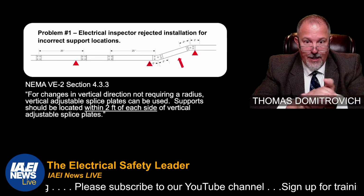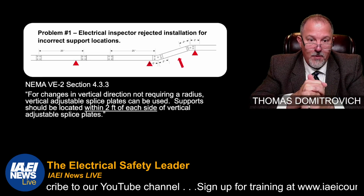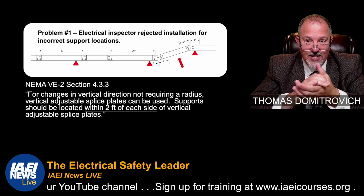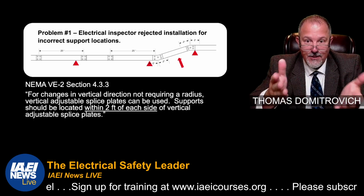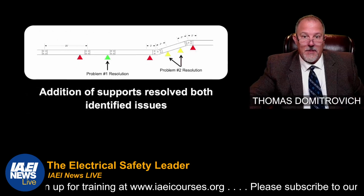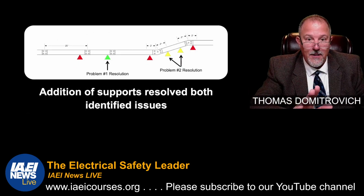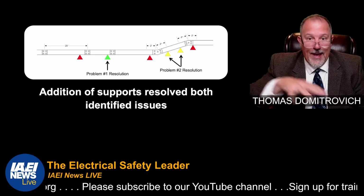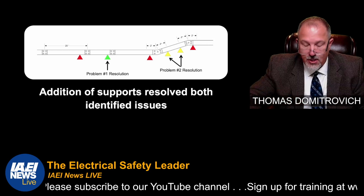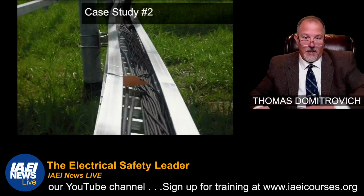Where not requiring a radius, vertical adjustable splice plates can be used. Supports should be located within 2 foot of each side of vertical adjustable splice plates. Look, there's another missing splice plate. This would have been the proper way to do that installation. The green and the yellows, that is where they should have added additional supports.